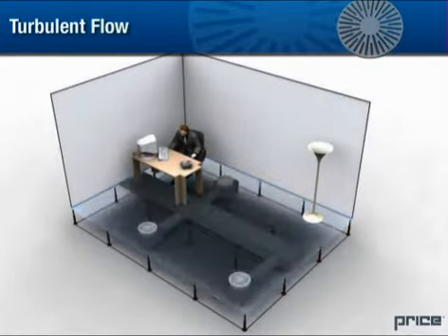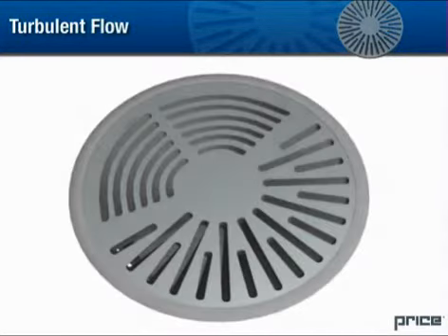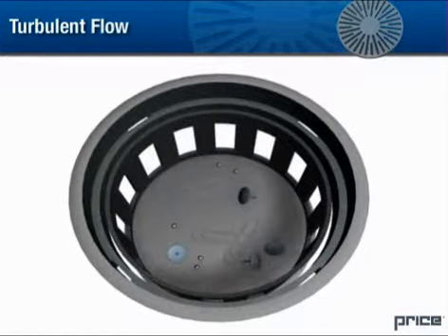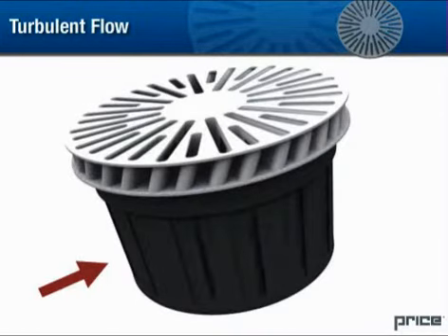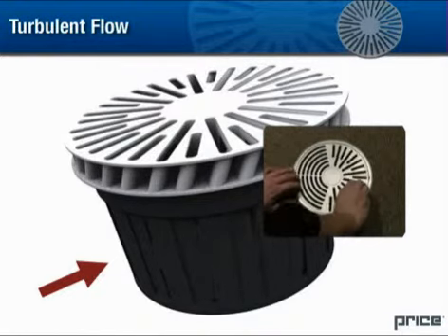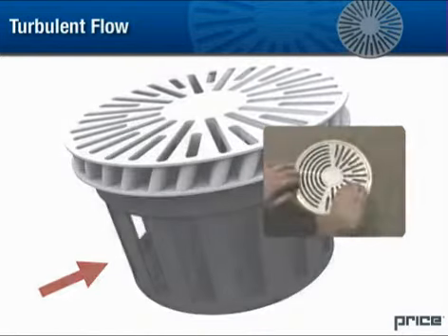The floor twist outlet is normally inserted in the floor tiles of the conventional raised floor system. A distributor basket may be inserted under the air outlet to trap solid objects such as coins and paper clips that may fall into the air outlets. In addition, some diffusers allow the volume and direction of the local air supply to be controlled by the occupant, allowing their local environment to be individually controlled.